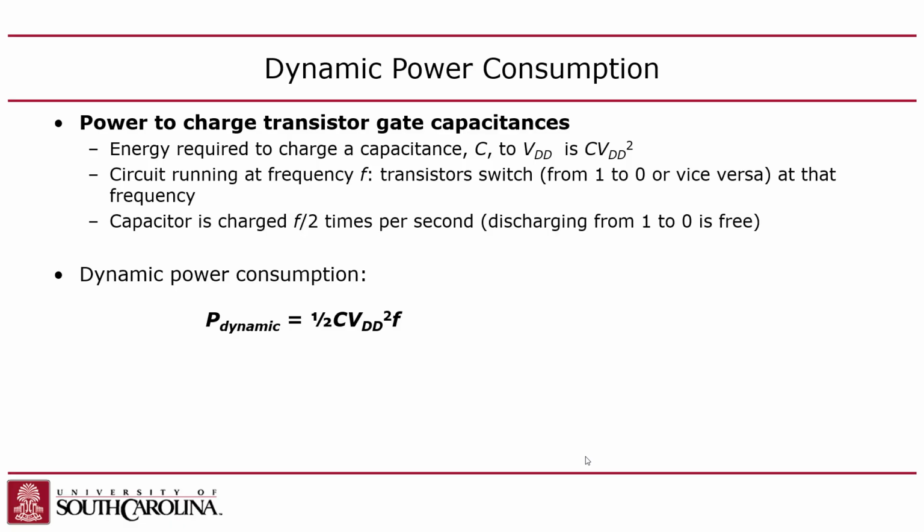Because either way, whenever you go from a logical 1 to 0, you're taking all that charge and you're just dumping it, right? You charge up a capacitor and then you're like, all right, goodbye, and you discharge it to ground. Kind of a waste, right? That's why, as I mentioned, for a long time one of the open problems is coming up with a way to recycle the charge, right? That would be huge. But at the moment, that technology has not become practical yet.